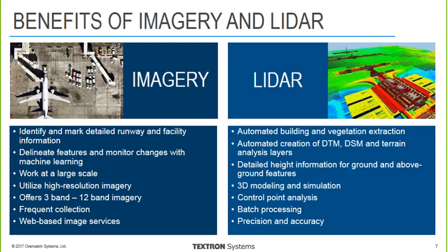We can see people on the ground, we can see lines, we can see runway lights, pretty much just about anything that we want to include in our airport materials database is in there. Okay, well that's great, but what about LiDAR? Well, LiDAR provides us with the height information, so we can fuse these two data sources together and get even more out of them. Coupled with automated feature extraction, we're not only saving time, but we're getting a higher accuracy product out of all of this.